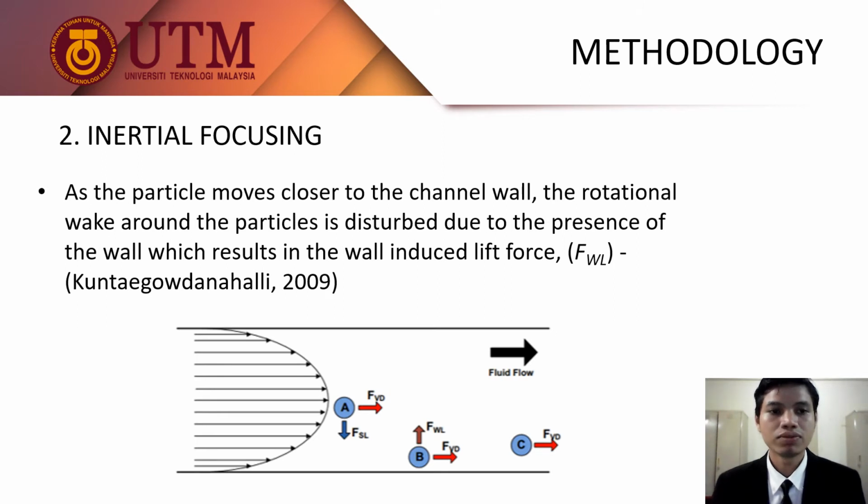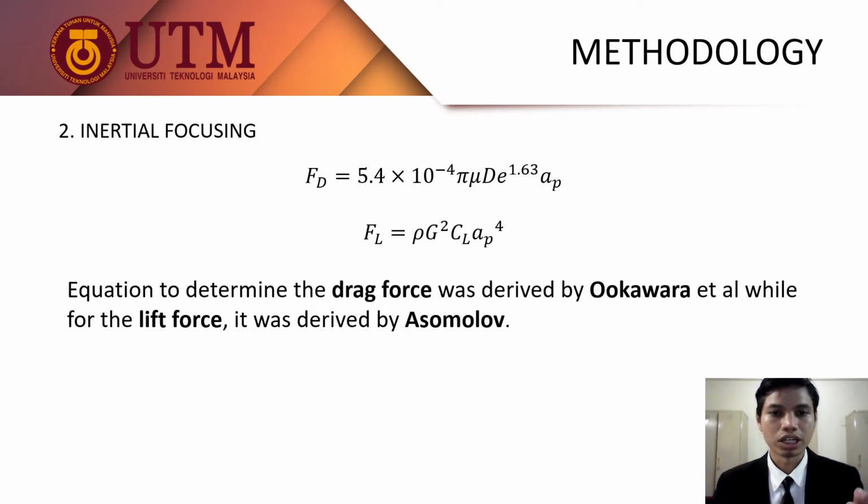Next is initial focusing. As the particle moves closer to the channel wall, the rotational wake around the particle is disturbed due to the presence of the wall, which results in the wall-induced lift force. It was cited from Kuntaegowdanahalli in 2009. So here are the equations for the forces that exist in the microchannel. The equation to determine the drag force was derived by Ookawara, while the lift force was derived by Asmolov.